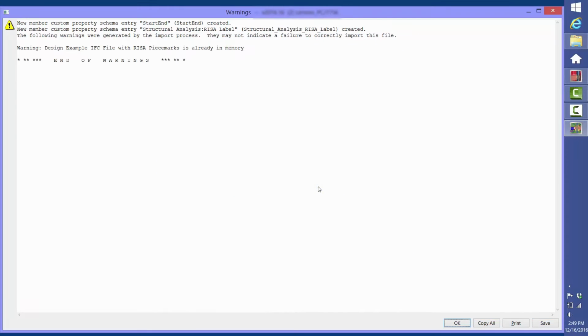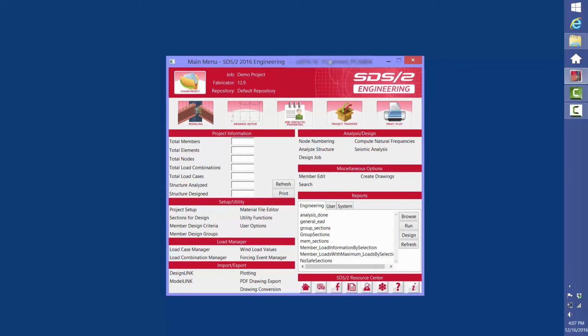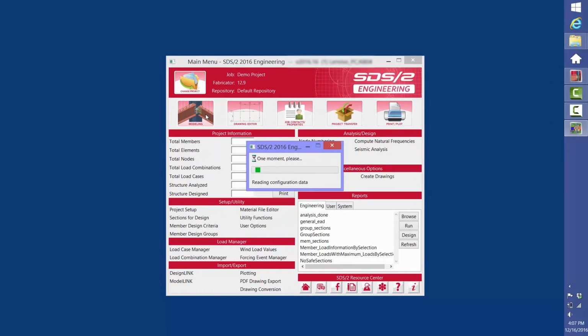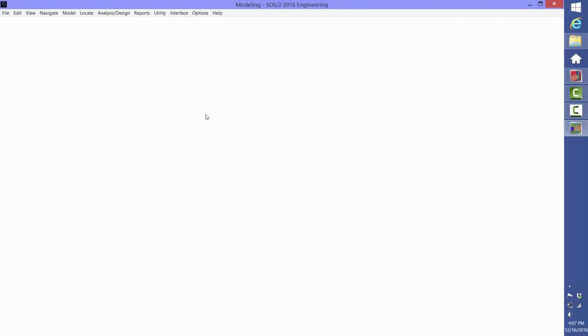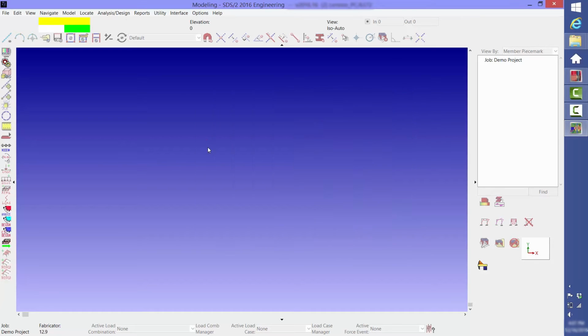To be completely honest with you, there is some cleanup work involved which is not part of this video. The cleanup work involves tasks such as adding base plates, moving brace work points to the half depth of beams, deleting material, and adding views. For this model, cleanup took less than 5 minutes. For a huge project with thousands of members, it might take a couple of hours.